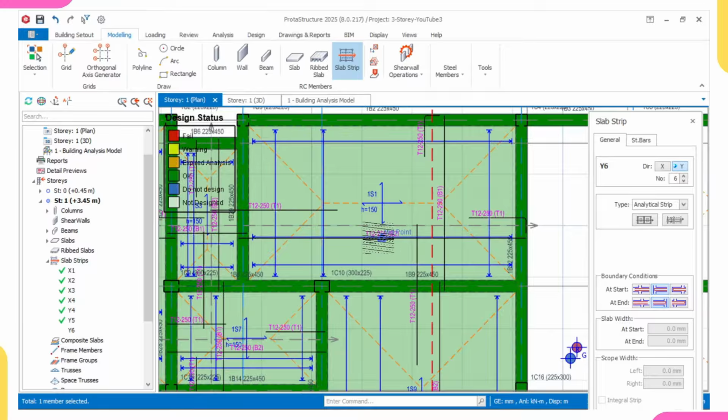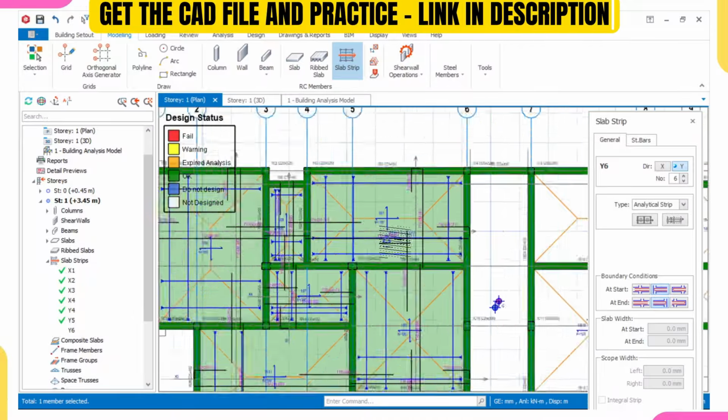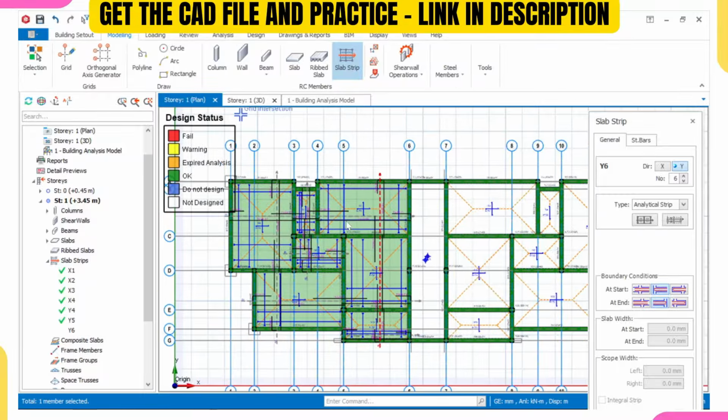In fact, I'll just advise you generally, once you come to slab, make sure that the minimum spacing that you use in slab, that's my advice, is 200. That should be your minimum spacing once it comes to slab. So with this now, I believe that we have come to the end of this video. So this is what we have done.